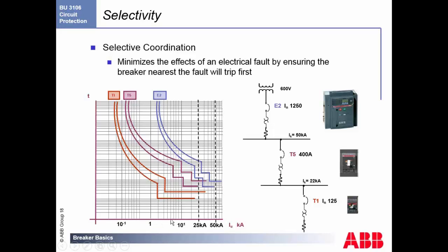So if I'm at, say, 1 times my nominal, you can see that T1, which is this tiny little breaker, that's almost your machine breaker, if you will, pops before T5, which is our branch feeder over here, pops. This means that any other equipment coming off this T5 will be running just fine, and all you lose is the downtime from this one conveyor belt.